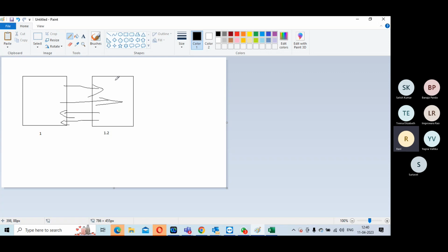And I will tell you how and why. Because if you add it in the 1 volt block, that means you have to boost to 1.2 volt. That means there should be another 1.2 volt supply over here. Here you can actually reduce the voltage from 1.2 and derive 1 volt. There you will have to increase the voltage, which means adding voltage boosters and current boosters. These are things that are actually required.